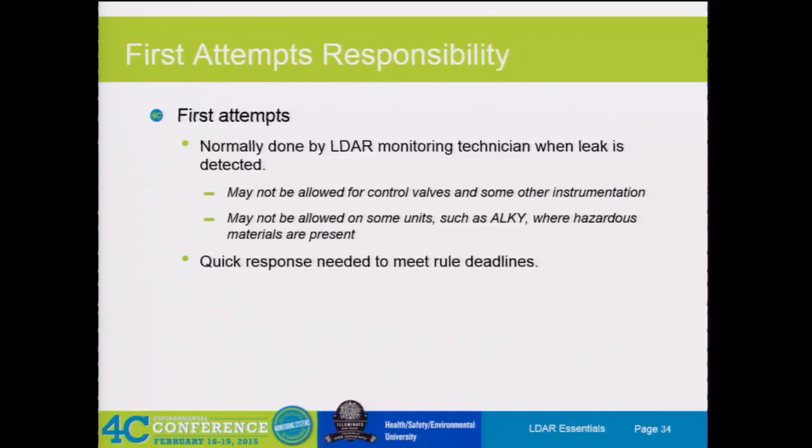Or how many people have seen where you have your follower that's bent like this? Has anybody seen that? Yeah. They've over-tightened it so badly that it's no longer holding the design specifications. They've tightened it down and bent that follower, so now that whole valve has to be replaced, and it creates a lot more of a mess. It's not going to get fixed ever. It's going to be leaking.